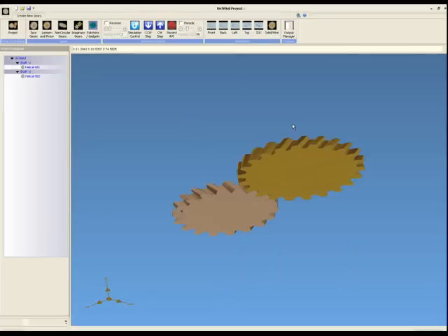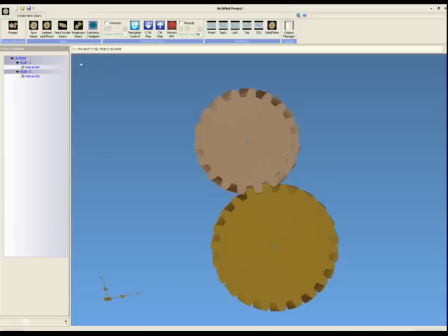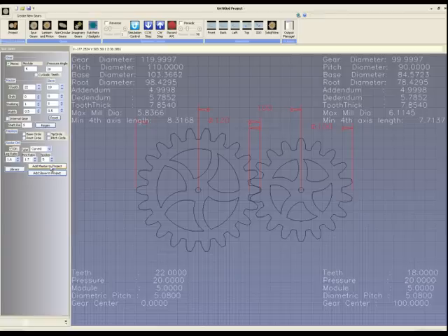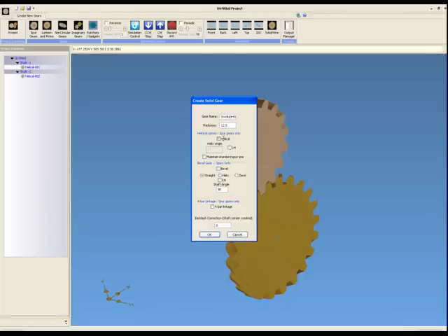That's not always the case with helicals, or not always the case that someone wants to do that with a helical. Let's take a look at add another helical to this project. We'll go helical, 45 degrees, and this time I won't check the left-handed box. This is to tell it that now I have two right-handed helicals that are going to mesh.